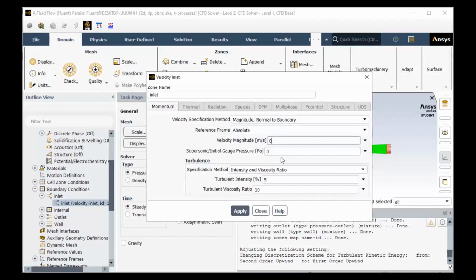we know that we were given the velocity at the center of the test section, which was, with the 20 hertz, the velocity in the test section was 4.61 meters per second approximately. So basically, you just relate that with the ratio of the diffuser areas, and at the end you get the inlet velocity, which is 1.25624 meters per second.